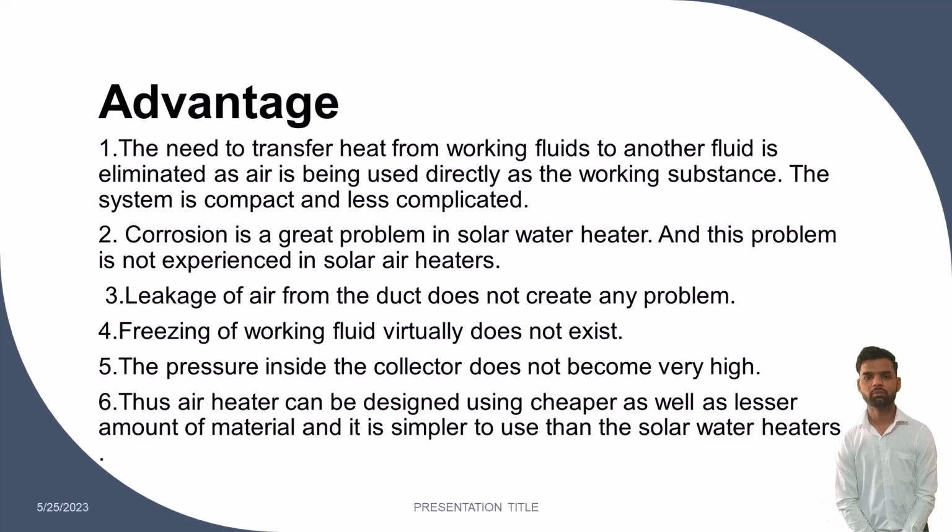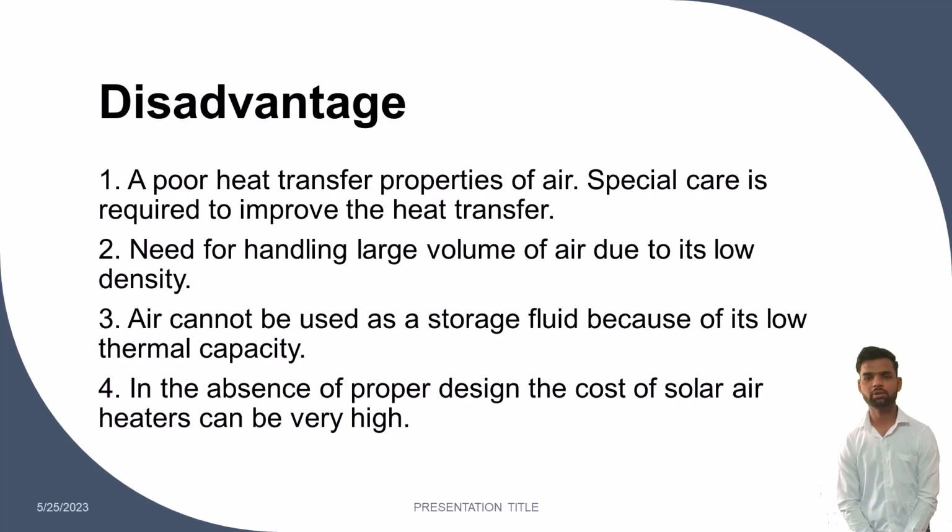Air heaters have certain disadvantages also. The first and foremost is the poor heat transfer properties of air. Special care is required to improve the heat transfer rate. Another disadvantage is the need for handling a large volume of air due to low density. Air cannot be used as a storage fluid because of its low thermal capacity. In the absence of proper design, the cost of solar air heaters can be very high.